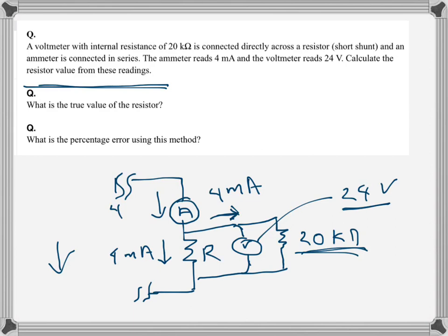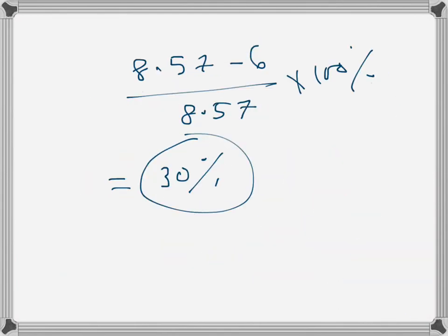So what happens is, voltmeter comes with a reading, and to measure the voltage drop across a 4 kilo ohms resistance, or when we want to find the value of the resistance and we know that the range is a bit high, we need to use a voltmeter that has a much higher internal resistance, because no voltmeter can be actually ideal in that sense, can't have infinite resistance, but it can have a very high resistance compared to this resistance, and that is very significant. So I will just talk about that a little bit.